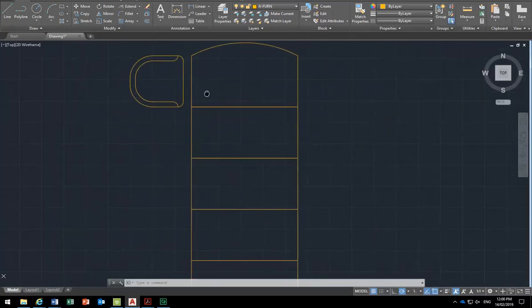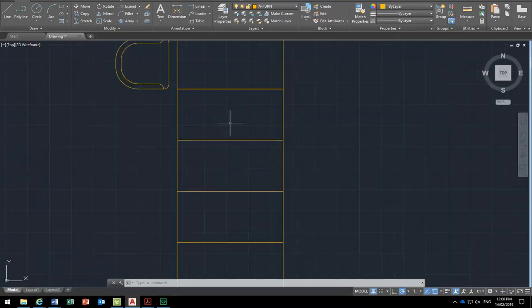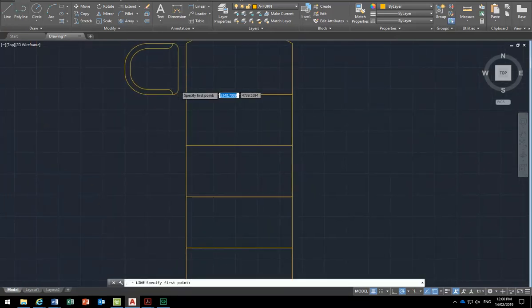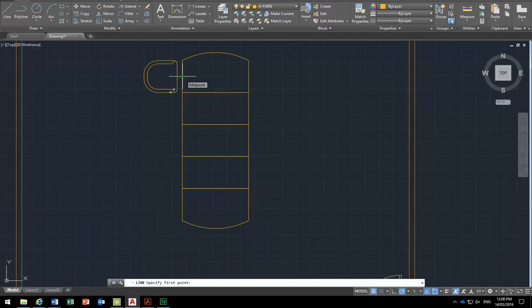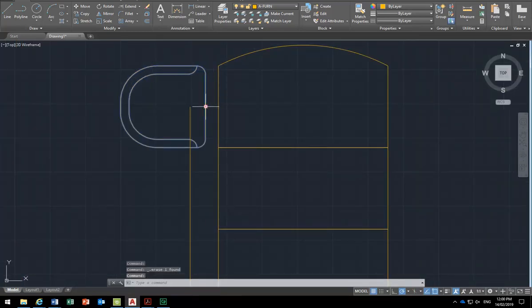So, yeah, so I think what they want you to do is draw a new line from the midpoint of this edge down to the midpoint of the equivalent edge on the panel at the bottom, and then offset 200. And before saying, don't be afraid to draw construction lines in, and this is just another one of those. So I'll delete that first line that I drew because that'll get in the way later, and then select my chair, and I can use that insertion point now to pick up the block and snap it onto my new endpoint.